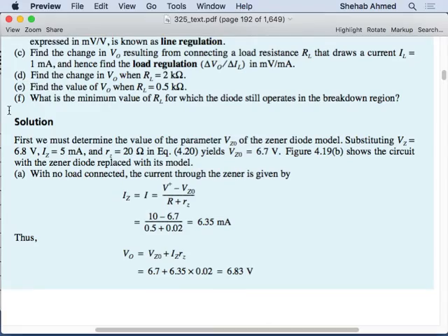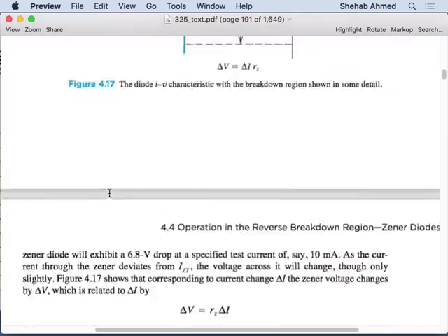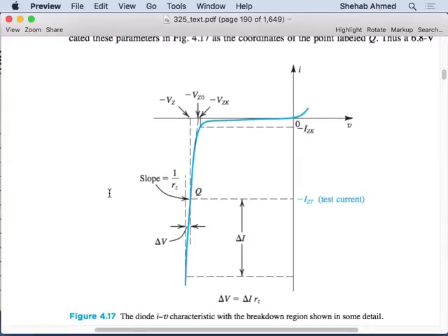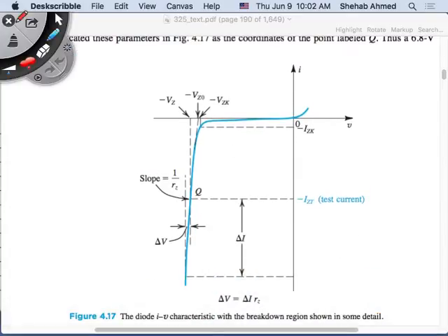Yes, but it doesn't matter. If you look at the curve here, what I was drawing is not a very nice curve, but look at it. Change the current. What's happening? There's a very abrupt change from Zener mode to non-Zener mode, because the slope here is very similar to the slope here, and here. There's an abrupt change in slope around the knee. Before that, the slope is very similar. So if the slope is similar, what does that mean? It means that VZ0 is not changing and RZ is not changing. Do you agree?